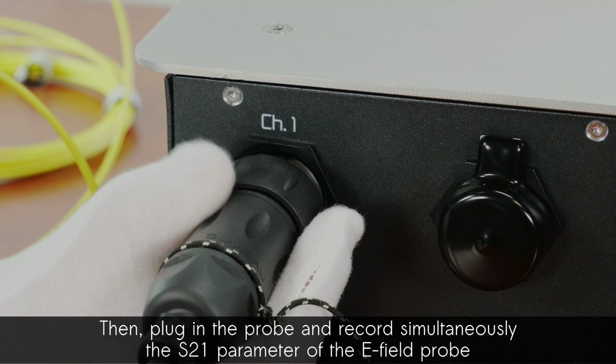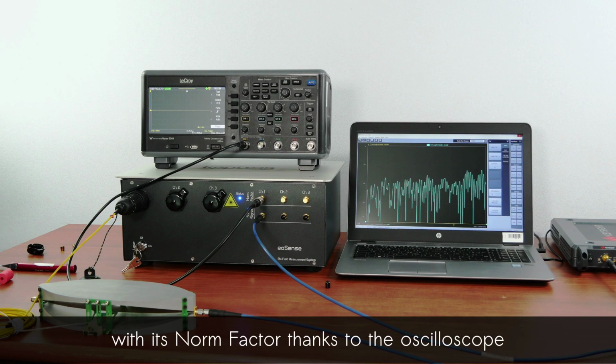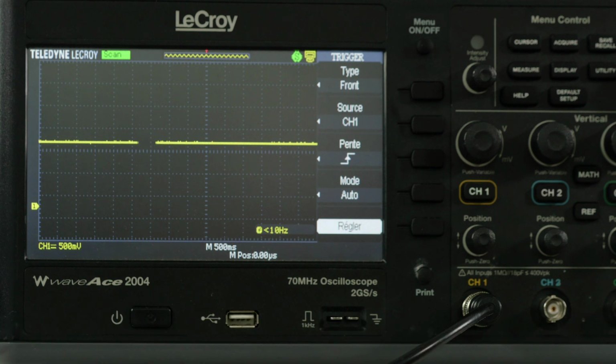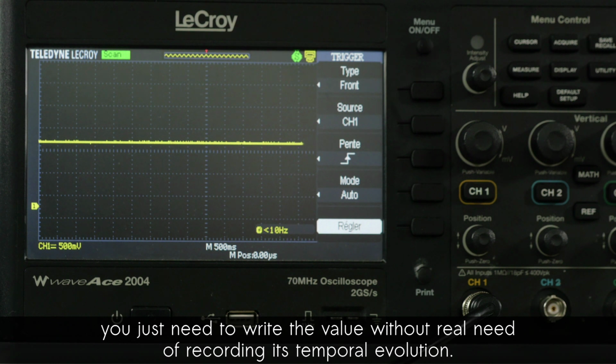Then, plug in the probe and simultaneously record the S21 parameter of the E-field probe with its norm factor thanks to the oscilloscope. If the norm factor remains perfectly constant like here, you just need to write down the value without any real need of recording its temporal evolution.